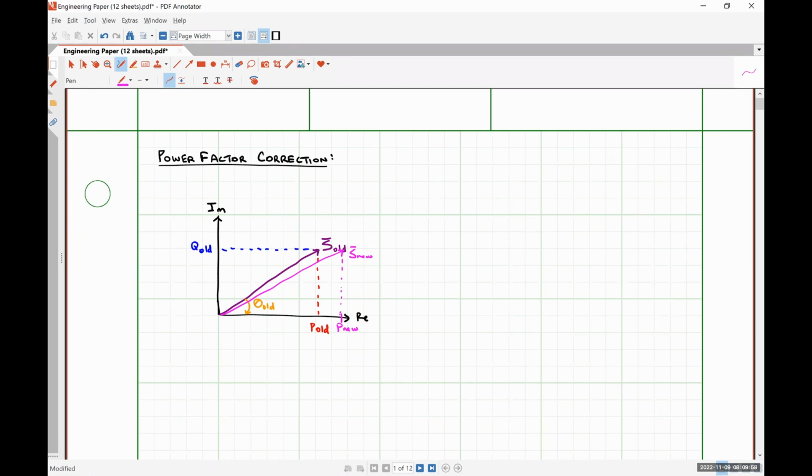So while mathematically it gets us the results that we want, practically it's the dumbest thing that we could do, okay? Because we would effectively say, in order to avoid this ongoing fine, we will pay more ongoing money. It's just the fine in a different form, okay? So increasing power factor by adding resistance is very, very dumb. So we're going to erase this because of how utterly stupid it is in practice.